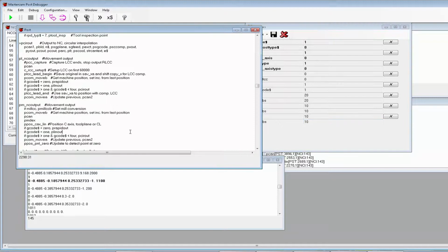Now, that's going to come probably next class. One of the things I want to focus on for the rest of this class is on making sure everybody understands how to program with a C-axis. So we're going to look at doing some lathe ops, some mill ops that are cross, either along the Z-axis or using the Y-axis mode. And we're also going to look at doing some face ops, some back-facing ops on the sub spindle, and understand setting up those tool planes.